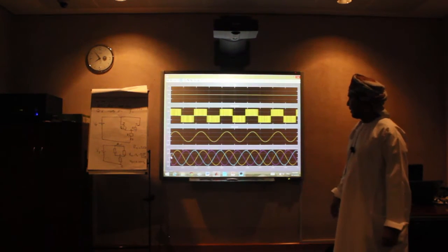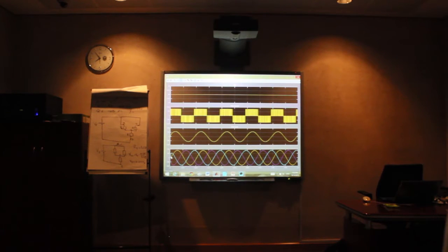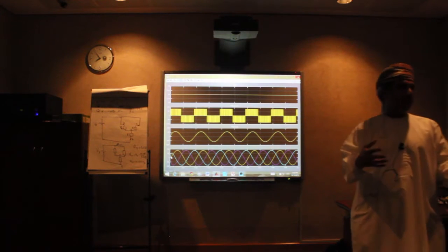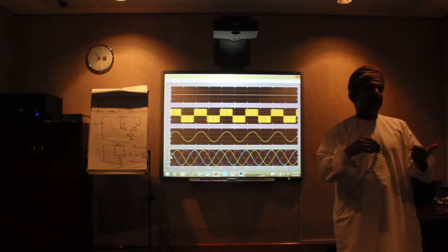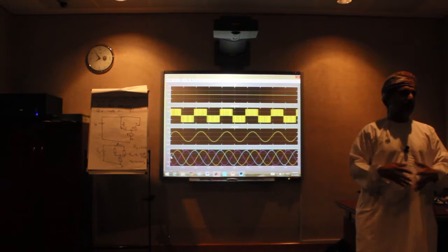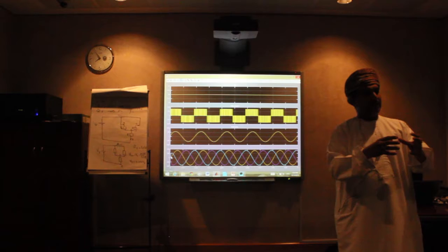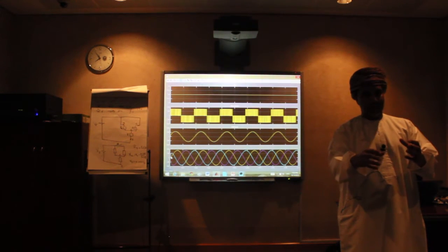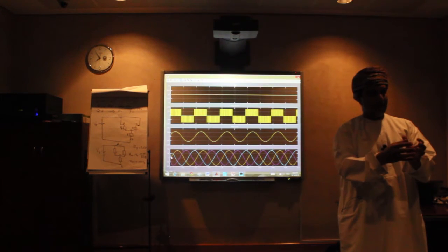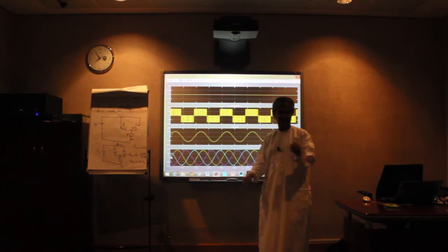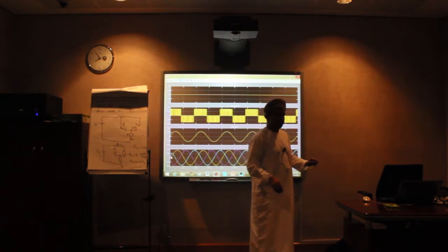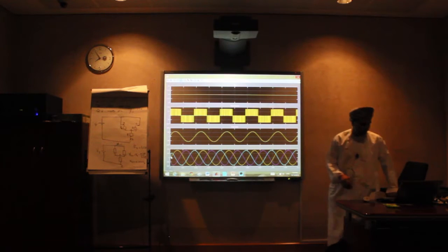But still there is noise. Yes, definitely, there is noise, because you need to smooth it, you need to increase the filter size. Or it depends also on the load. For example, if you design like what you have seen in the first video and you change the load, the ripples appear again, right? The same thing. You have an LC filter. You can block the transfer function of the resistance, which is the load, and the LC filter, and see the transfer function between this input and the output, and you will determine what the filter will do. I will show you in the project which the students have done last year.